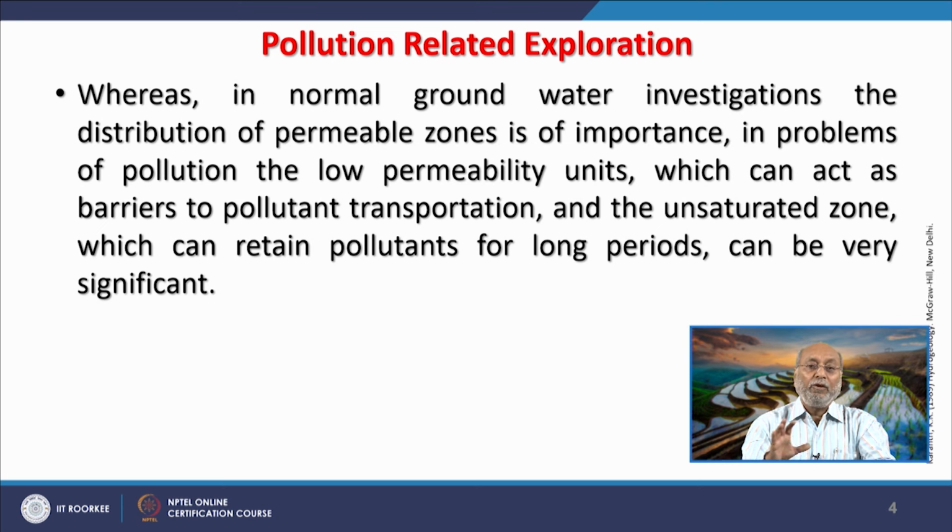So, proper disposal of even legacy waste will at least maintain a good quality of groundwater, because when these waste sites were selected in the past, maybe 20 or 30 years back, people probably did not think that this was going to cause harm. What is related to these waste sites are the leachates: when rainwater falls, slowly the water goes downward, and it carries whatever pollutants there are to the groundwater aquifers. So, these leachates have also become a big problem.